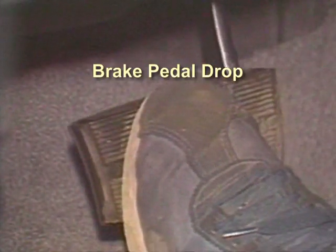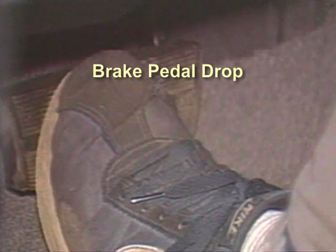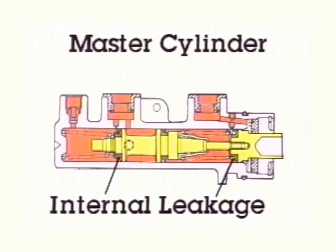Another problem is brake pedal drop. When at a stoplight, the brake pedal slowly moves toward the floor. Pumping the pedal can momentarily restore the pedal to its normal height. When this happens, it indicates a bad master cylinder. The master cylinder is usually leaking internally and must be replaced or rebuilt. Fluid level in the master cylinder reservoir may not drop because fluid is leaking internally.